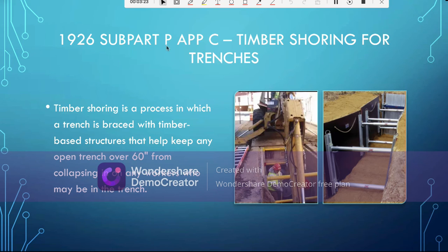1926 Subpart P, App C, Timber shoring for trenches. Timber shoring is a process in which a trench is braced with timber-based structures that help keep any open trench over 60 inches from collapsing in on any workers who may be in the trench.